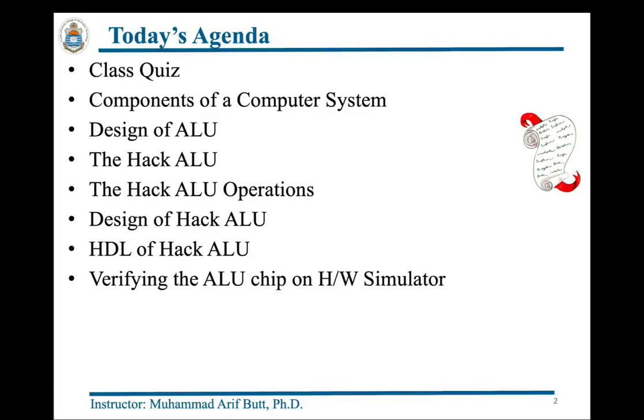Well, today we will start with a short class quiz. We will talk about different components of a general purpose computer system and we'll see where the ALU fits in this architecture. Since the target of this part of the course is design of the hack computer, today's target is the design of an ALU for this hack computer. We will write the HDL of this ALU and finally we will verify the ALU chip logic by loading and running it in the hardware simulator.